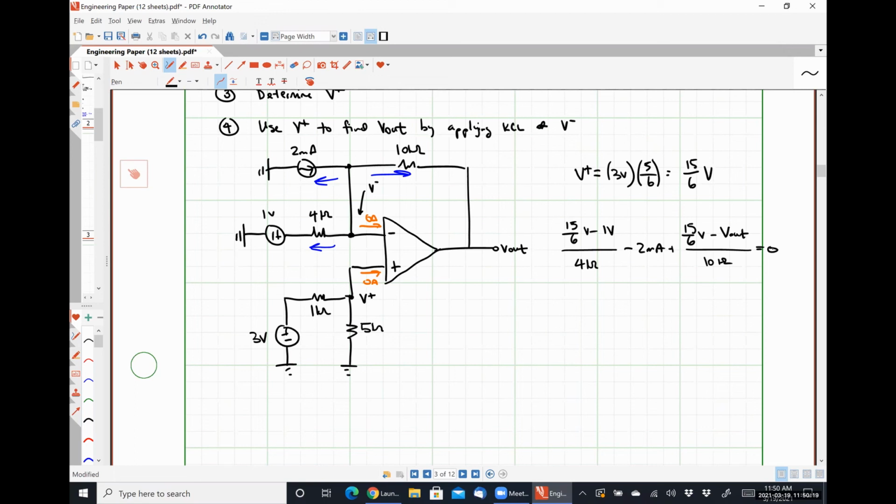So it's going to be practical op amp type stuff. One of your options might be to develop a better 1-bit analog to digital converter. We did one that was really crappy with a comparator. One option is to do one with a Schmitt trigger. Another option might be to set up a circuit to be used at a weigh station. If you have a 4-axle vehicle that drives across load cells, sum all of those input signals together and convert that output signal to the specific weight of the vehicle using resistor ratios.